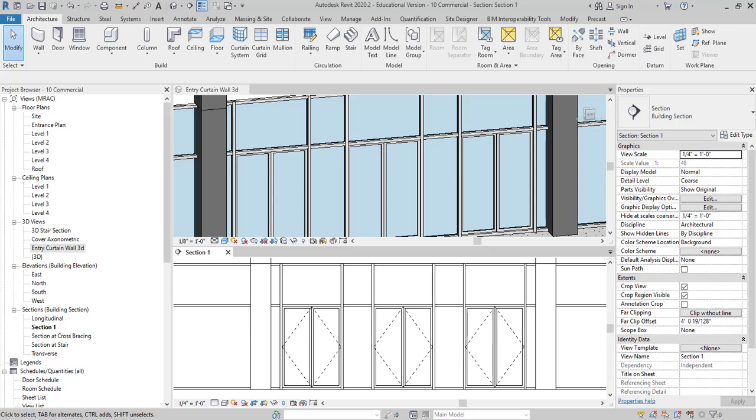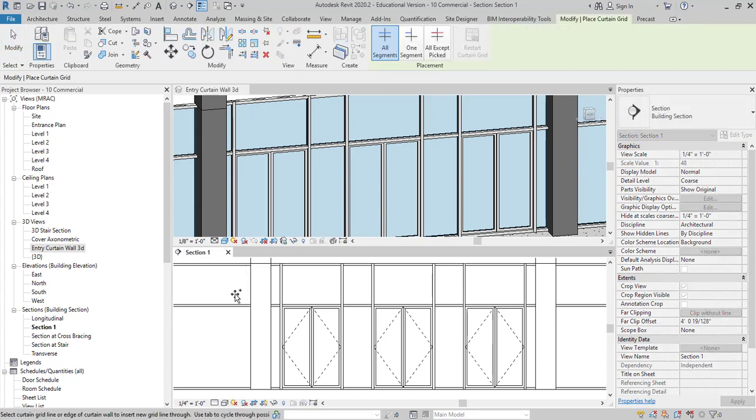So this next little portion is going to show us how we can supplant one of the panels of the wall with another wall system, not just a door or a piece of glass, but we can actually use the panels as a way to design walls. And so what I'm going to do here first is create a new curtain grid 1 foot away from that edge. And remember, you've got to hover over one of the horizontal lines in order to get a vertical curtain grid.